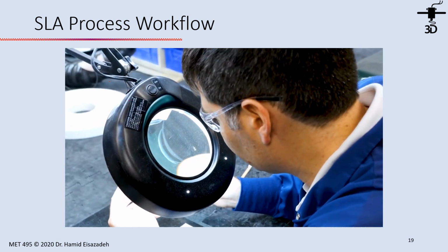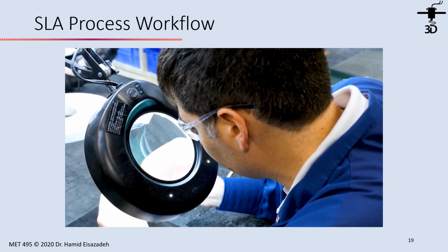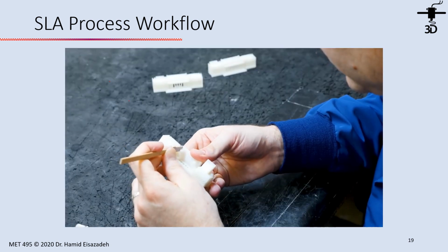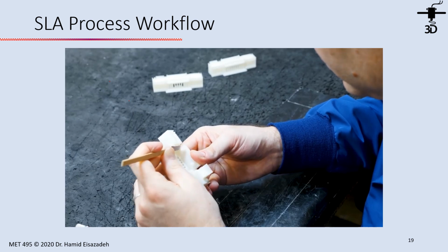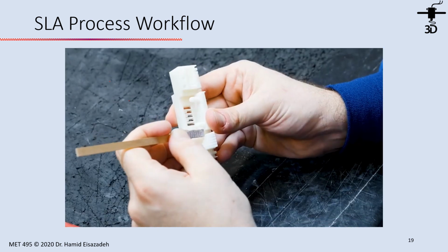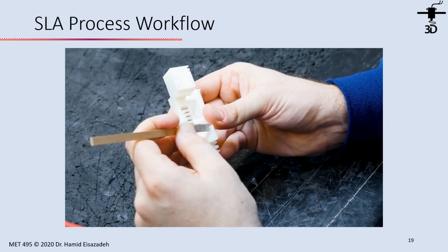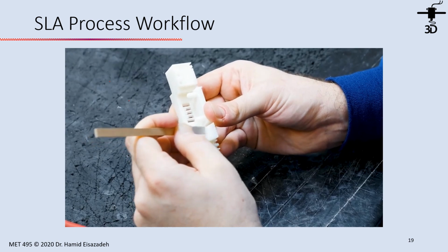After post-curing, he must clean up the fine details. He removes residual support on overhangs and in hard-to-reach areas. And at last, he briefly sands the base to make sure it's flat.